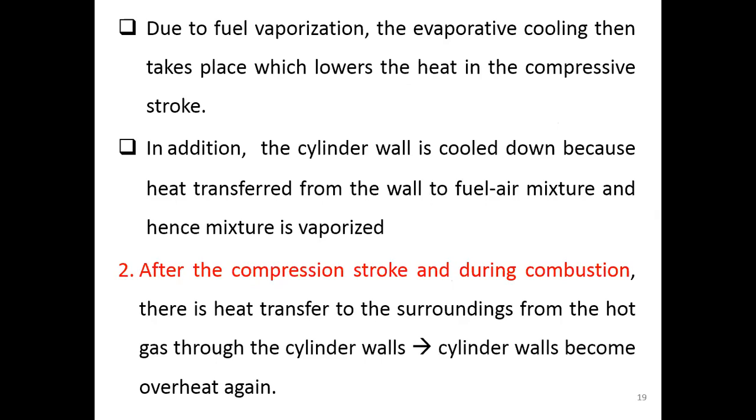Because the fuel vaporization draws heat from the cylinder wall, the wall itself gets what we call evaporative cooling. This will lower the amount of heat in the compression stroke.